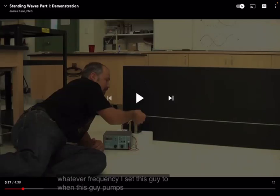The reason is it's a lot of power. If no antenna is connected, it's an open circuit. Your gamma equals 1, your V0 minus equals your V0 plus. Everything's getting reflected. You're getting these peaks and nulls, and that could damage the electronics as it comes back. Okay, let's see if we got some volume now.